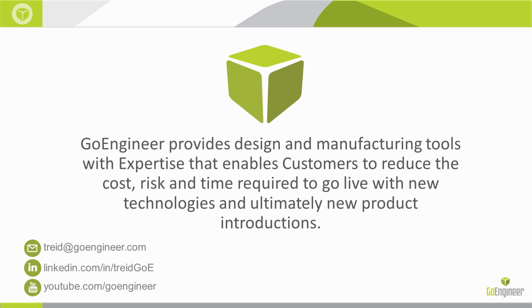So that's about it. I promised 15-20 minutes on this webinar, and for once I actually adhered to that. The CAMWorks Sync Manager is an essential tool for any CAMWorks user using the twin turret lathe. Otherwise, you have to go through and program out those two G-code files, and the operator, or again, the programmer, has to go in and manually add those wait codes. There's really no way around it. So to be able to do that inside CAMWorks with just a pick and place, something that you can really pay attention to what you're doing and keep track of all of the steps, is essential.